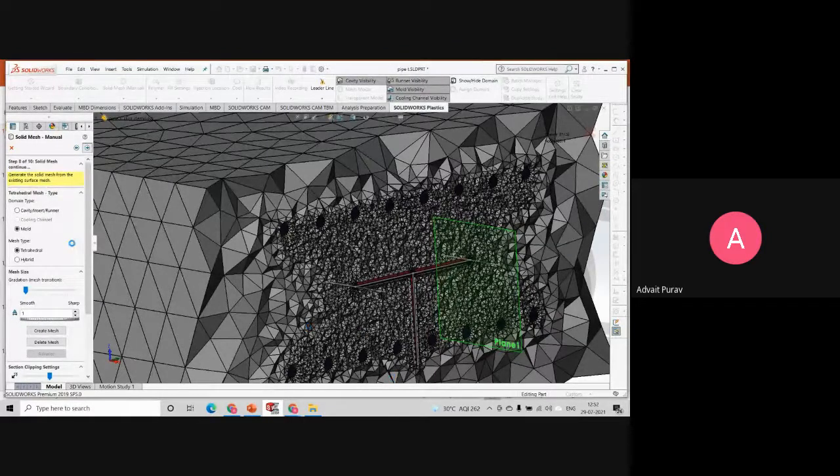No sir, it is a clipping plane. There is a clipping plane down here, and he has done this himself. Yes, that is what I'm saying, he has halved the meshing himself, and he will run the analysis for half of the component, because the other part is the same, right? Yes sir. See, here he is showing the mesh for only half of the side, so the overall simulation will also run for half of the size, because the other half is the mirror of this.